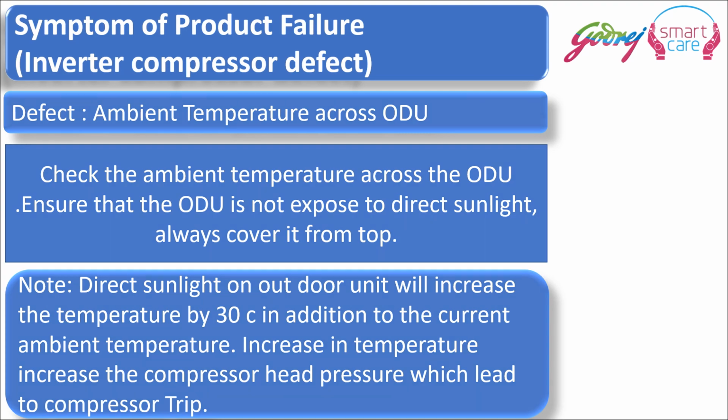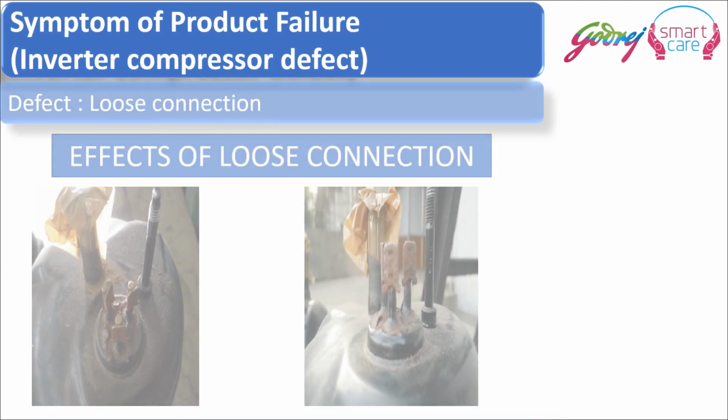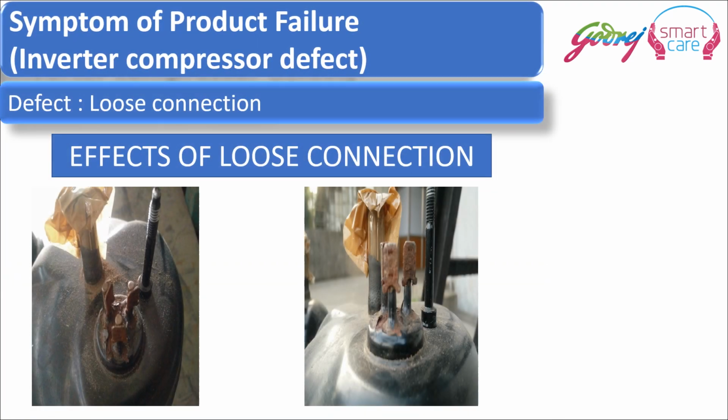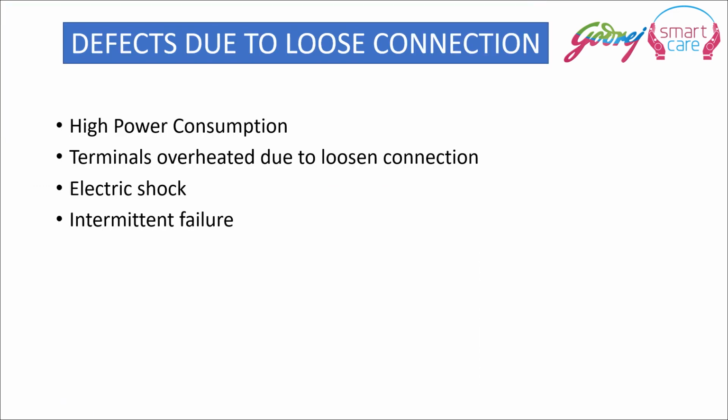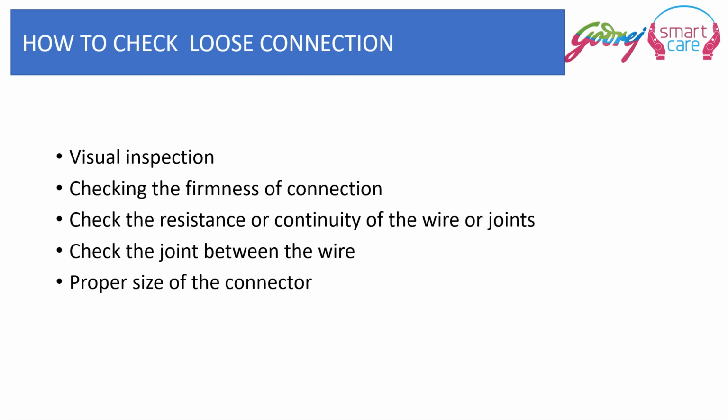Now the effect of loose connections. We will ensure that the wires are properly connected to the terminals. The defects which arise due to loose connections are high power consumption, terminals overheated due to loose connections, electric shocks, intermittent failures. How do we check the loose connection?